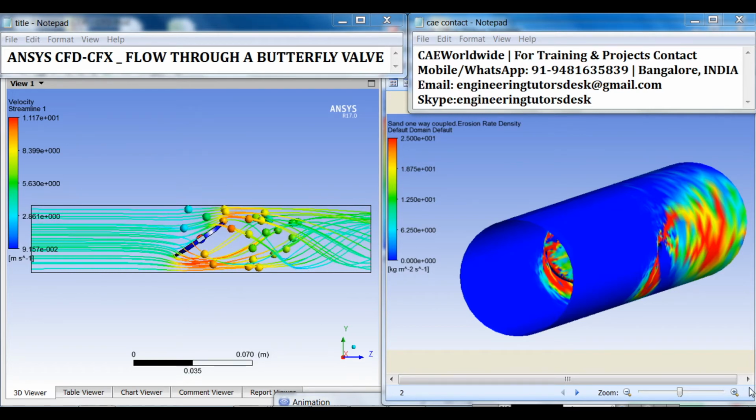After defining materials for analysis, we have to define boundary conditions. For the inlet, we have to create a fully developed inlet velocity profile using the CFX expression language. A fully developed fluid flow through a pipe is one in which the boundary layer extends to the center line. Hence the maximum velocity of the boundary layer is the same as the center line velocity of the pipe.